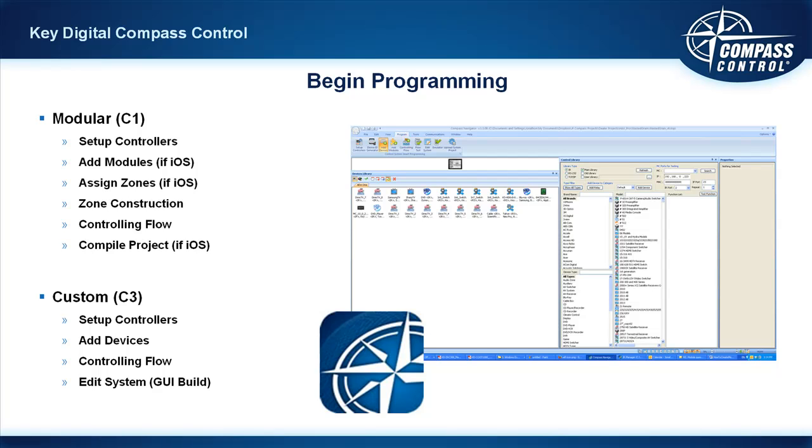Modular systems, again: a modular system has the events and actions already on the module and already on the button. So if I press the Blu-ray button, it should automatically have on it the macro that is needed so that the TV is on and switches to its proper input, and then the switcher or AV receiver is on and selects its proper input so that the Blu-ray player is what you are viewing on the display, right?